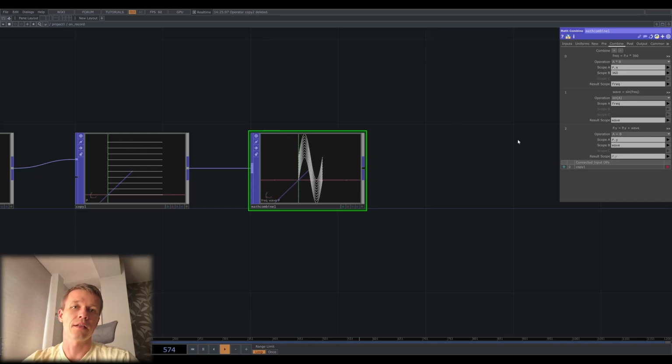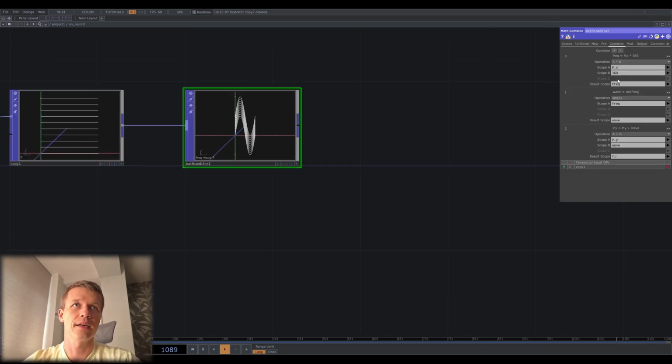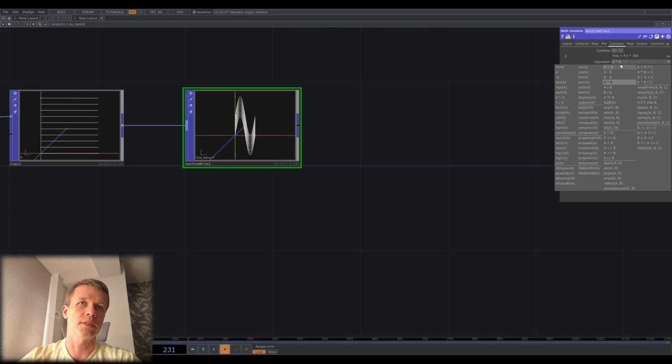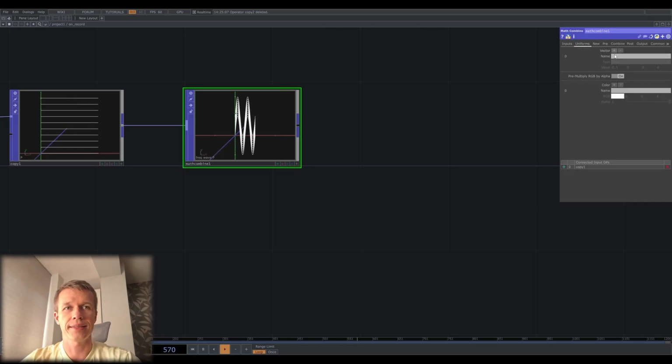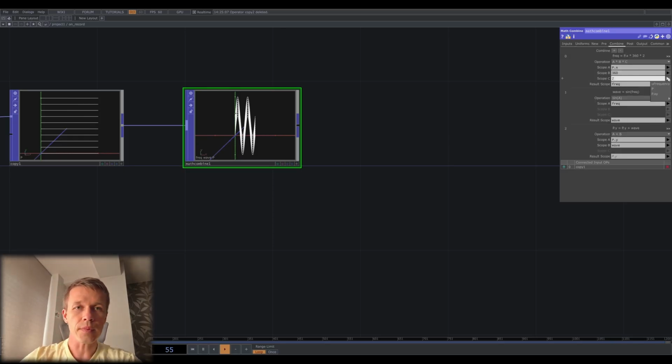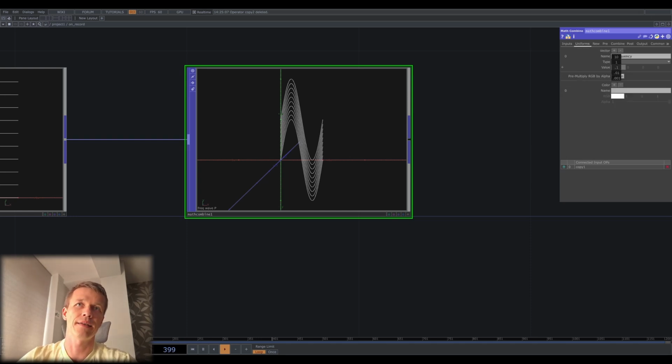At first, the wave doesn't look too wavy. This is because the sine operation in Math Combine expects degrees. One full sine cycle is 360 degrees, so I multiply the value by 360. I will also increase the number of points in the line, so the wave is smooth. But pay attention, if you build the same operation in GLSL POP, the sine and cosine will use radians instead of degrees, so we'll need to multiply by 2 times pi instead of 360. So now we have one full wave across the line. If I multiply the phase by 720 degrees, we get 2 full waves instead.